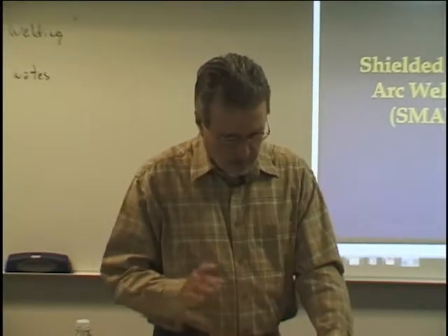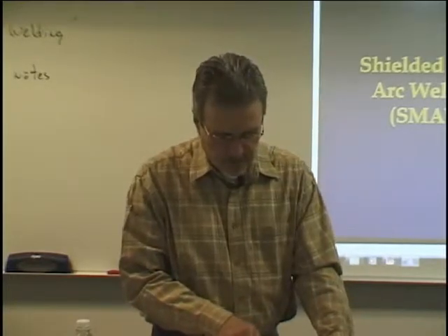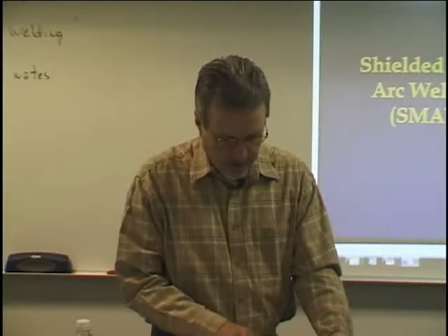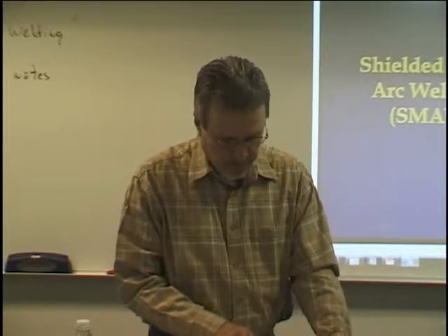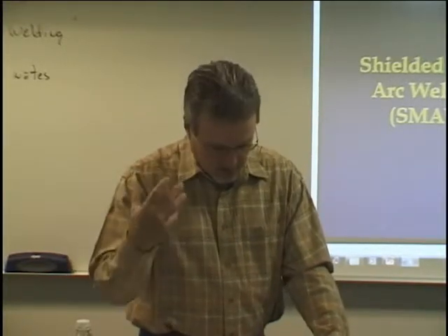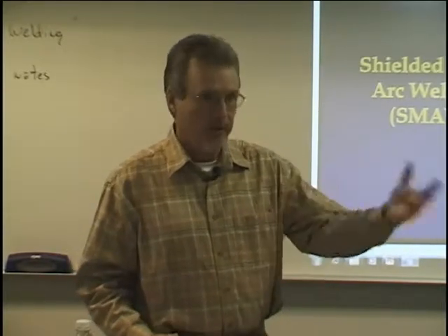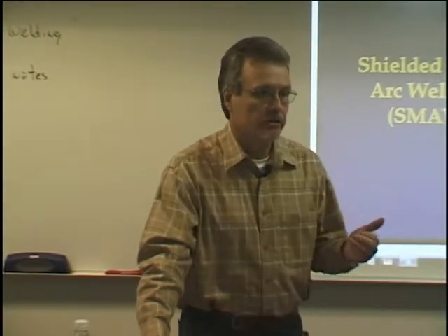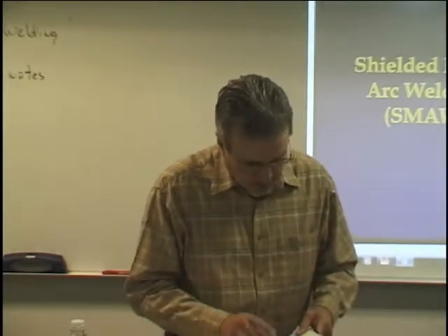Here we go. Briefly on acetylene, I'm reading on page 146. It says, commercial acetylene is made from calcium carbide, which is commonly referred to as carbide. Carbide is a gray, stone-like substance that is the product of smelting coke and lime in an electric furnace. And then they dissolve that in water, or what they call an acetylene generator, and they actually manufacture acetylene in that way. Acetylene has the greatest BTU production of any of the fuel gases that we use. So that's acetylene. So that was a bullet.